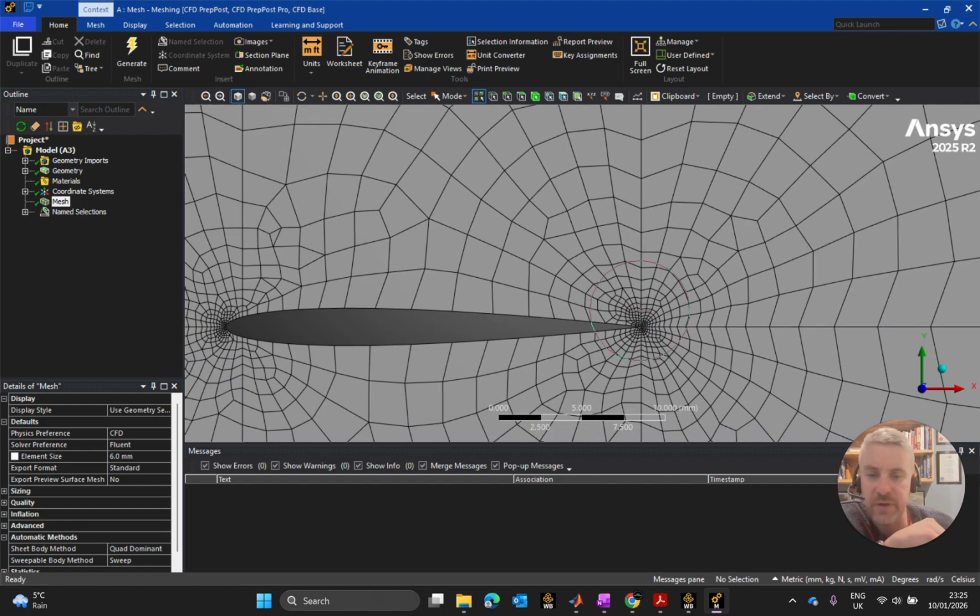A lot of things are varied, and bearing in mind that within discretization the physics are solved at the centroids of each of these elements, the value at the center of a cell will be a function of what's happening in the cells around it. The bigger those cells are, the more error there is.